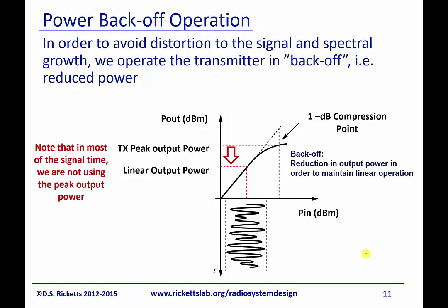The other challenge is if we operate such a system down here, let's say, as our quiescent point, it has a lot of DC power that's able to create these higher output powers. So even though we might be down here operating nice and linear, typically the system will be inefficient because it has a great deal of DC power necessary to create high output power.